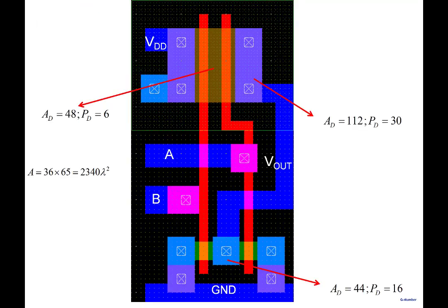And so the layout, one possible layout for the NOR gate is shown over here. The two transistors are in parallel here, NMOSs are in parallel. One end is connected to ground, the other end is common. So the two NMOSs here are in parallel, and the two PMOSs are in series. One transistor here and the other transistor here, they are in series, and the outputs of the transistors are connected together, so you have V out here, and you have input A. A is for us the upper transistor here, and B for us is the lower transistor here. Lower meaning lower compared to the output here.